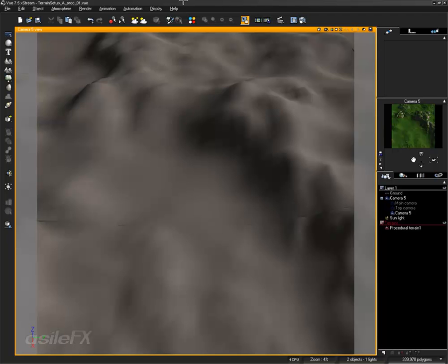And if you find out that you want to change this to an animated scene, and you need to create different projection cameras, move around the scene, and render new spots to work from, you can't do that with standard terrain or the projected map that's going to be on this. So if we needed to get this detail and back over here, we would need to face that camera towards that area and re-render with the procedural. So it's really important that you have this scene as the procedural before going over and converting it.